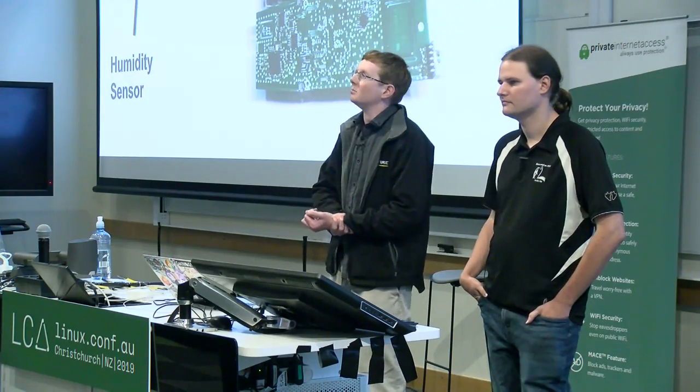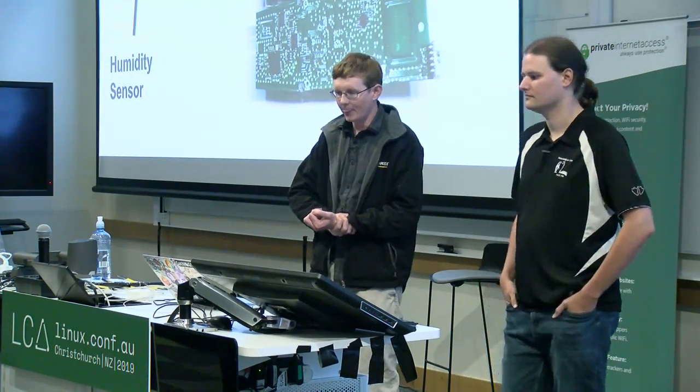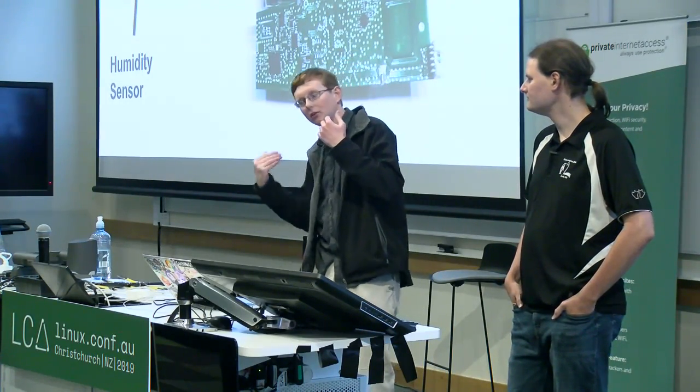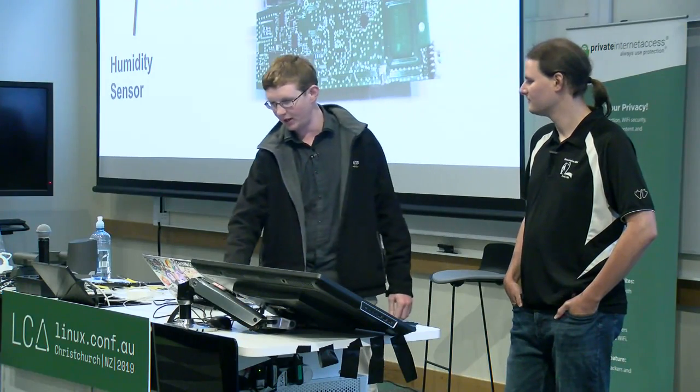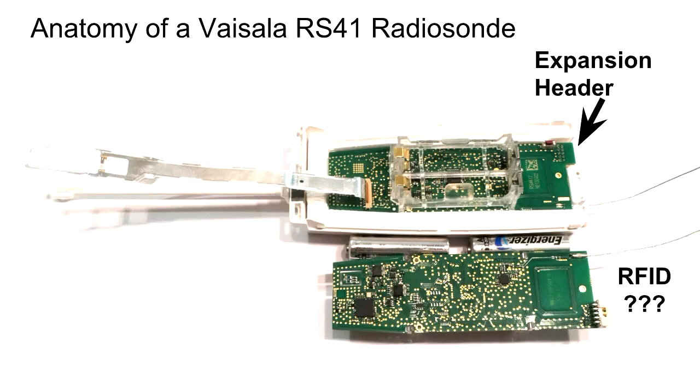Vaisala have implemented their own analog to digital converter on the PCB. Yeah, my analog knowledge kind of fell out of one ear a few years ago. I haven't quite figured out how to drive it yet. Last but not least, we have a couple of external interfaces. There's a 10-pin expansion header, which is where things like those ozone sensors might plug in. And there's also this weird little coil on the board, which is actually used to program the sonde, at least set the frequency prior to launch, and run a few calibration routines as well.